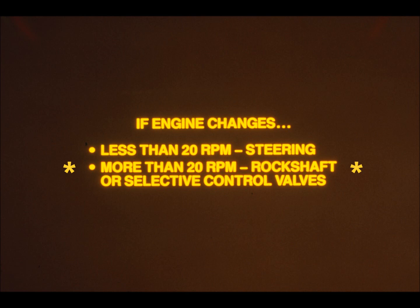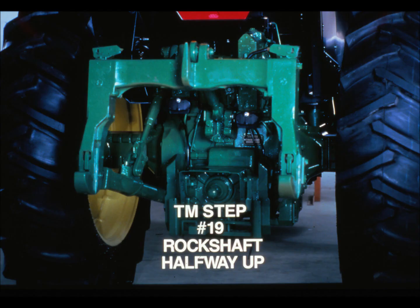If engine speed changes more than 20 RPM, high pressure oil is still leaking to return. The leak is somewhere in the SCV or rock shaft. The technical manual then directs you to go to step 19. To isolate the leak, step 19 tells you to position the rock shaft halfway up.